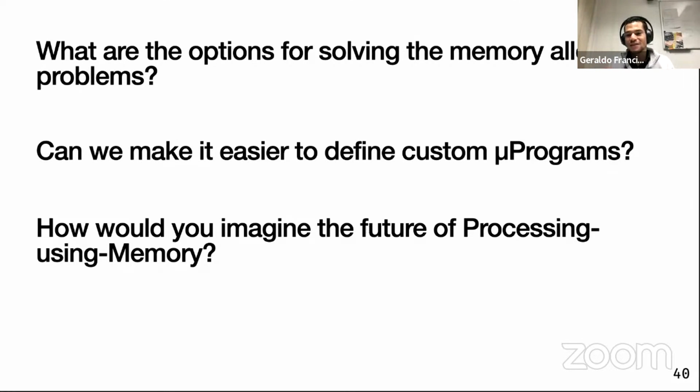But then every time you need to normalize the exponents, you need to bring the data to the CPU or to the transpose units, to the CPU control units, transpose all the data again, one by one, figure out which decimal value you have in the end, and then issue the amount of operations that you need to do in DRAM, which is extremely costly and goes a little bit against the paradigm that you are working on.